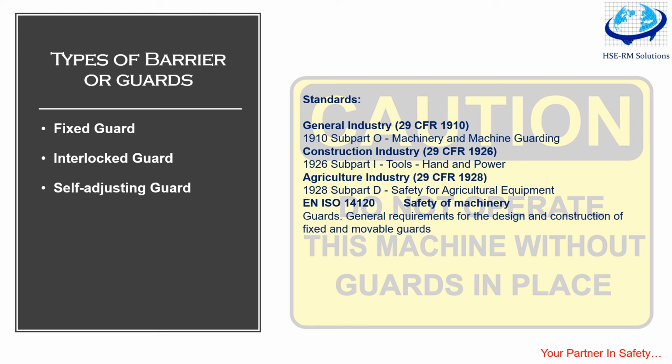Self-guarding guards serve the same purpose as an adjustable guard, but automatically adapt to the size of the material. When the machine is at rest, these guards sit all the way down. When the machine is in use, the operator feeds the material into the machine, which opens the guards just enough to let the material in. These guards are commonly found in table saws and woodworking tools, etc.